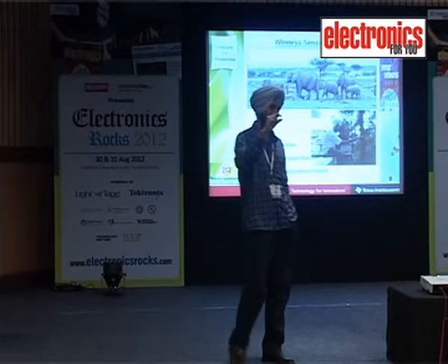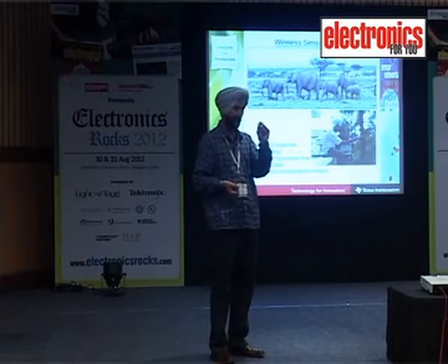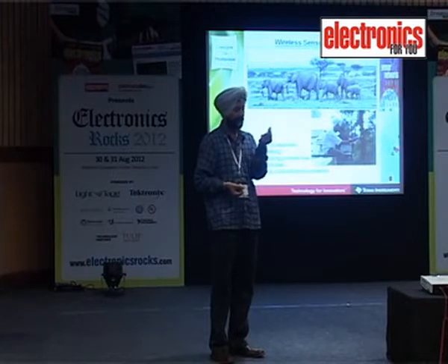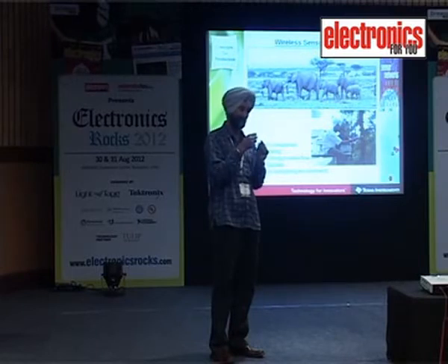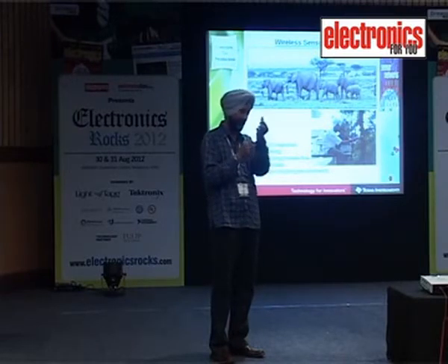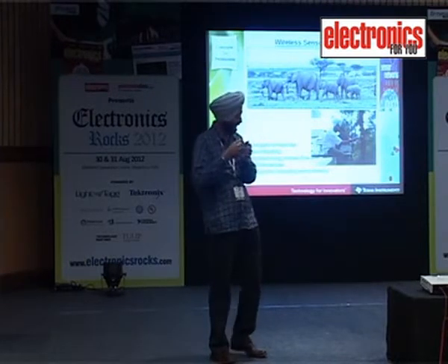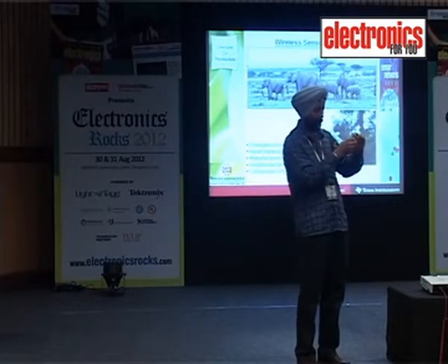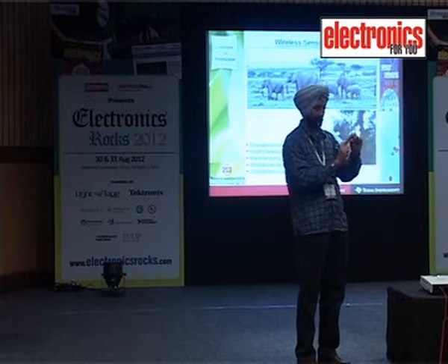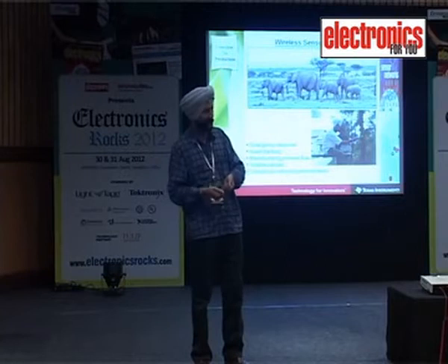Now first, you must have seen the small bottles of homeopathic sweet pills. We have done some experiments. We can make a very small PCB, maybe 8 millimeters in width and hardly 10 millimeters in length. This kind of PCB with MSP430 plus accelerometer and battery is packed in a small bottle, hermetically sealed. Now you drill a hole inside the tree, push this bottle into the hole and seal it.